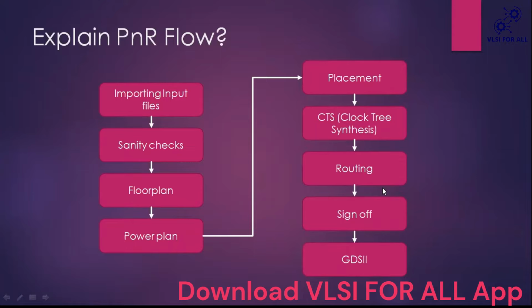Another thing is timing sign off, that we say STA, static timing analysis. We have to do all these things during sign off. One thing you have to remember here is that sign off tools are only analysis tools. PNR tool is an implementation tool.